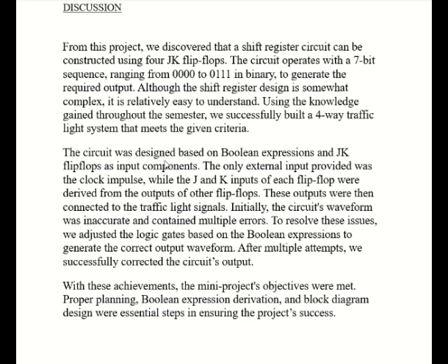The circuit was designed based on Boolean expressions and JK flip-flops as components. The only external input provided was the clock impulse, while the J and K inputs of each flip-flop were derived from the outputs of other flip-flops. These outputs were then connected to the traffic light signals.